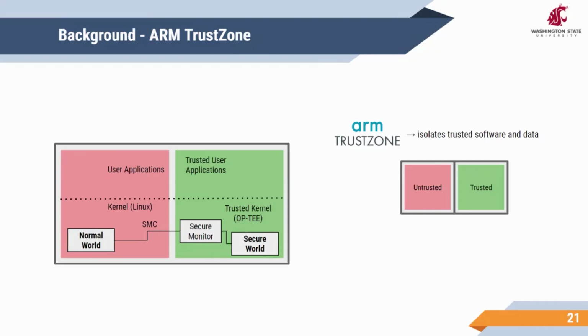Now, if we use this TrustZone technology to secure the actuation command or check the actuation commands, we need to take care of this overhead of data transfer between normal and secure world, because we need to transfer the actuation command request from the normal world to the secure world, and then in the secure world we could do some additional checking.